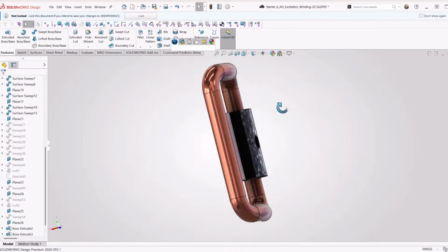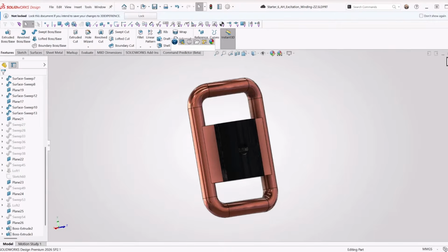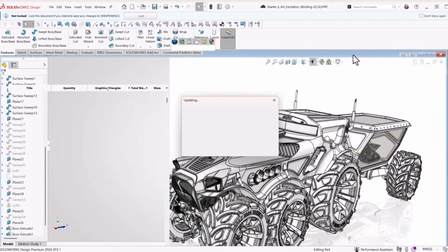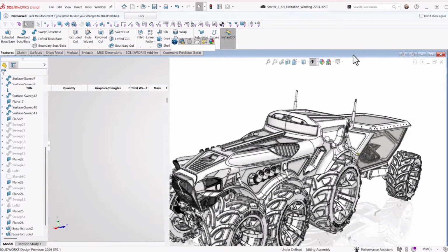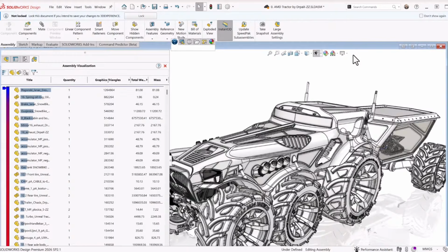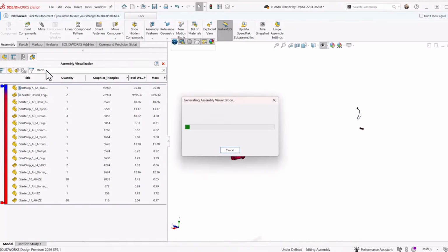I really like how you called out that that is a document property. I don't think a lot of people understand that, because most software has an application property, where you turn down the quality so that it loads faster. Well, this is the actual document property. It lives inside that part, so it's reducing the size of that part, increasing the performance of where that part is used, and that lives with that component as you move it from assembly to assembly.